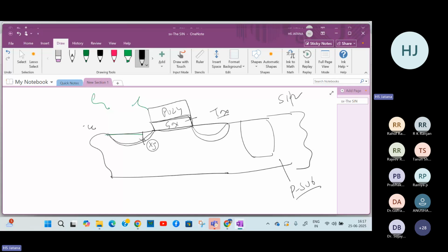There is some nitrogen, 5%, 10% nitrogen in this to make a better transistor, because here the channel is found below this interface, and adding nitrogen here affects the mobility. So your ID sat is better. Our ID sat is 600 microampere per micrometer. You can check there. So what is their VT? Our VT is 420 millivolt. Their VT will also be within the same range, maybe 15-20 millivolt here and there.